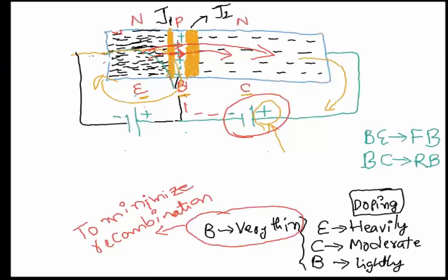So that's how. This junction must be forward bias between base and emitter, meaning that you require at least 0.7 volts right there. This junction is usually reverse bias, so depending upon the limits, you can put 1 volt, 2 volts, 3 volts. Of course, with that small voltage, you're not going to have any current. But so that's the electron current. So now you're going to have current basically emitter to the collector.